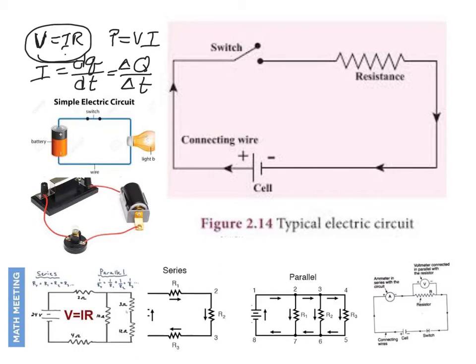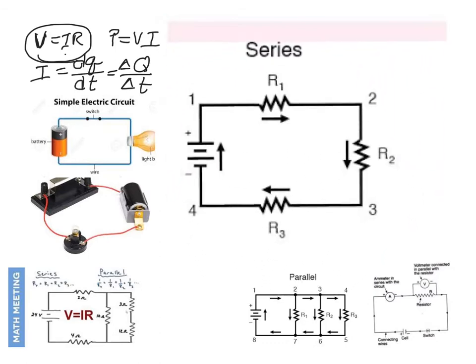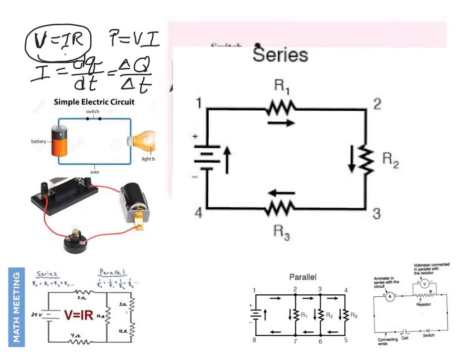And you'll see when there's more than one circuit element, it's important where you put the meter. So if I put my meter, so one lead was here and one lead was here, I would be measuring the voltage across the battery or the voltage across all 3 resistors. So if I just want to know the voltage across this resistor, I would have to put the 2 leads here, with the meter in parallel with R1 or R2.